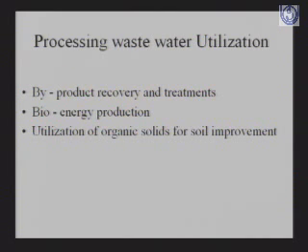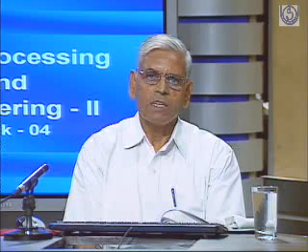It has soluble solids which require a lot of oxygen for fermentation, and they settle down in the tanks. The solid is utilized as compost or other feed materials, and the liquid is clarified without any organic components and is fed into the sewage water or the canal system.